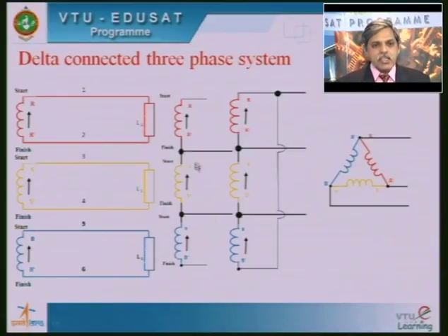Now by connecting these, the R phase, Y phase and B phase voltages are all in series. Forget about the line I have taken; just by making the connection, all three are connected in series here. Now when I try to make the third connection, the finish of B phase to the start of R phase, I will be making a closed loop.